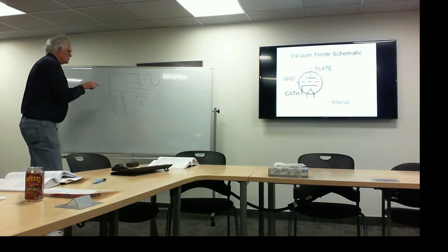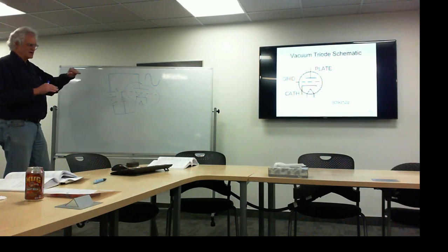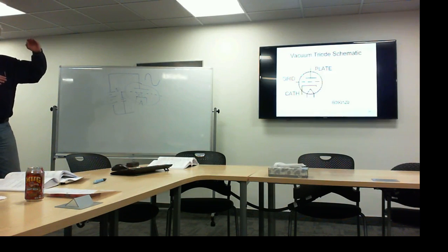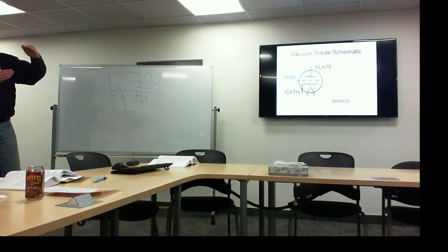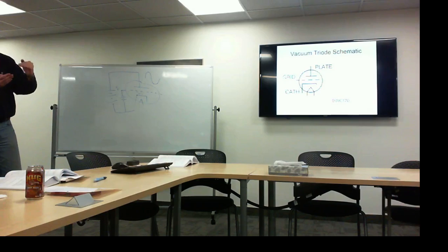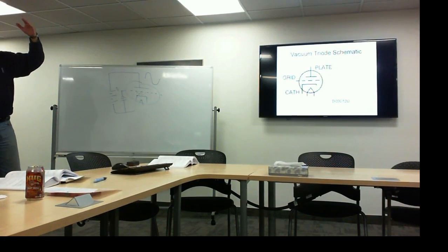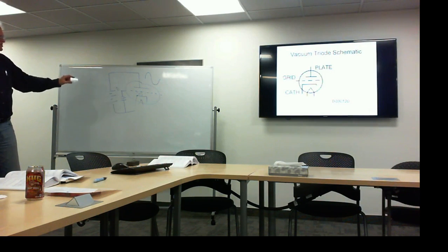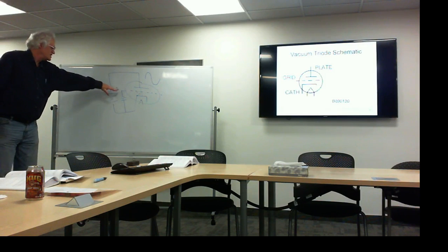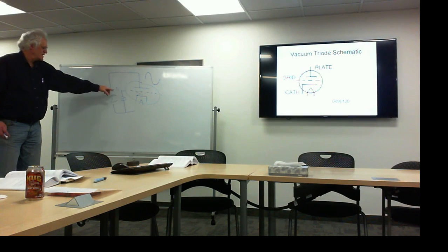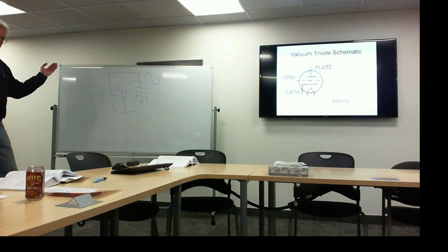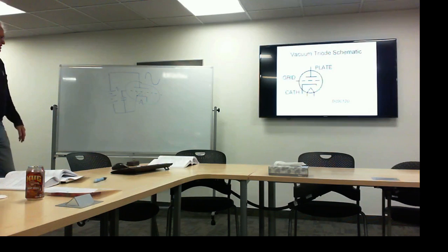No, because you vary the point where you have it conducting to a certain point, but you actually have the signal varying it up and down. So in other words, as your voltage goes one way, you'll let your conduction increase, and as it goes the other way, it'll decrease the current. So you'll actually have it sitting at some point, and then you apply the AC on it, and it will just vary. You don't have it turned all the way on or turned all the way off. You just have a point.